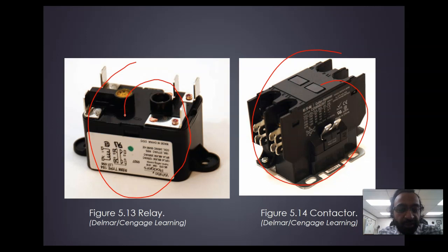And when you did the multimeter lab, I had you go and test a relay and see the contact and see if there's sound or not. Those things are really good to touch and get very close to and do testing for all those connections in it. So if you look at this contactor, there is current going through this line and this line, and it's disconnected in the middle.